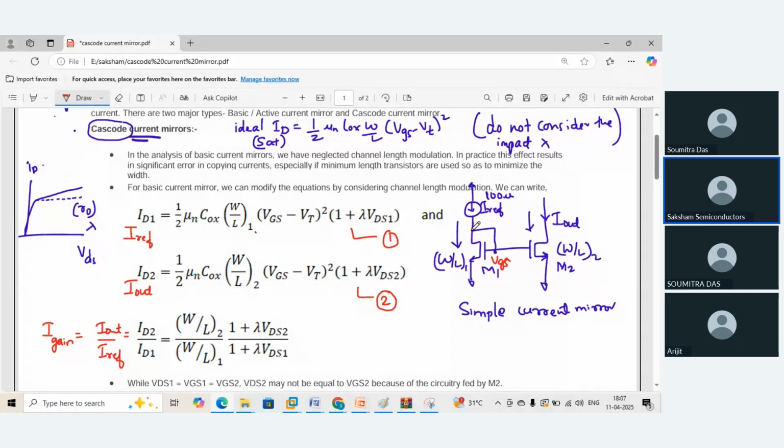If you observe over here, you can consider point number X and point number Y. Whether the voltages at X and Y are the same. Now the answer to this question is definitely they cannot be same, because the voltage X here, which is nothing but my VDS value, is decided by this current source and what VDD you are supplying, and whatever drop occurs, whatever value you get, that will be your VDS, which is marked here as X.